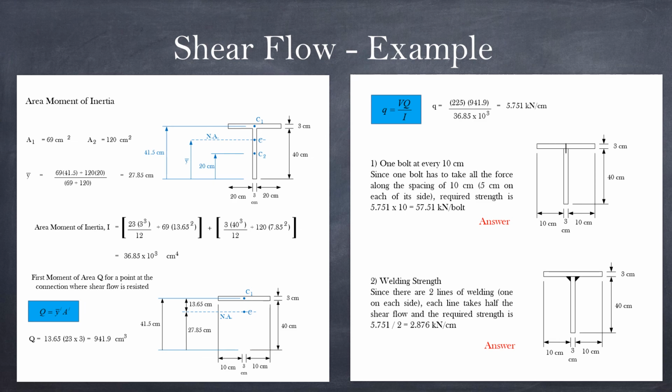And of course, next, if you really want to build this, you have to go out and find, if you use option number 1, a bolt that can take this amount of force, the same as welding. If option number 2, you have to use either the technique or the brand name that can actually guarantee that you have this kind of strength. And that's it for our lesson today.